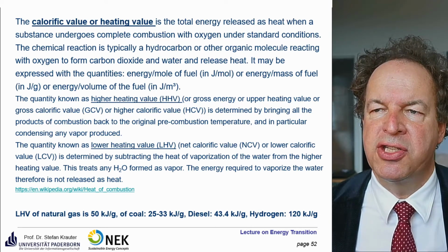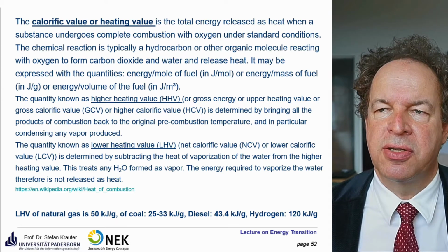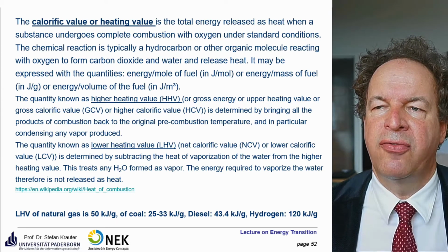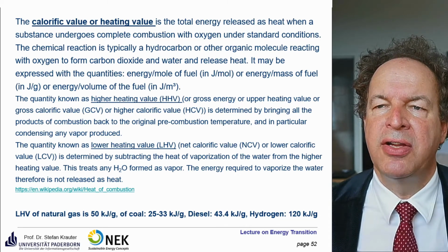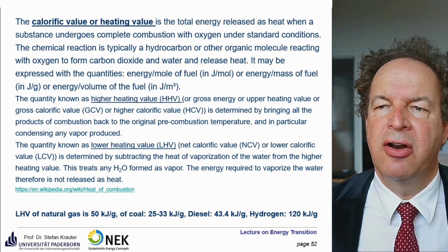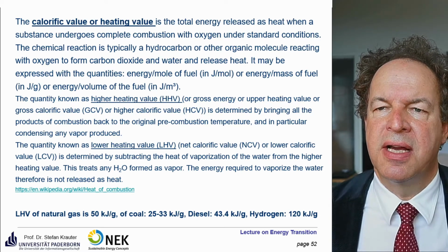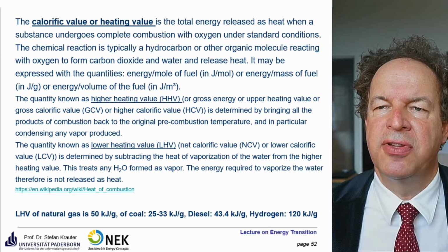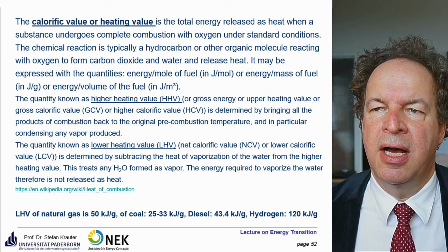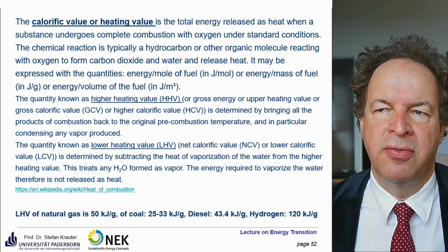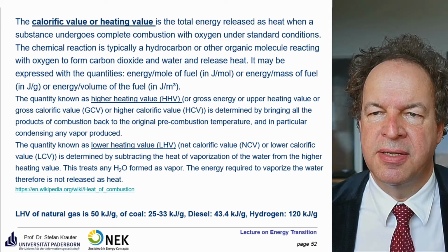It contains some water which has to be evaporated, but which cannot be used directly for the combustion process, and therefore for us the so-called lower heating value is more important. That's the net calorific value, and we subtract the energy needed for the evaporation of the water that is contained in the material. For example, wood or even coal have some water content.